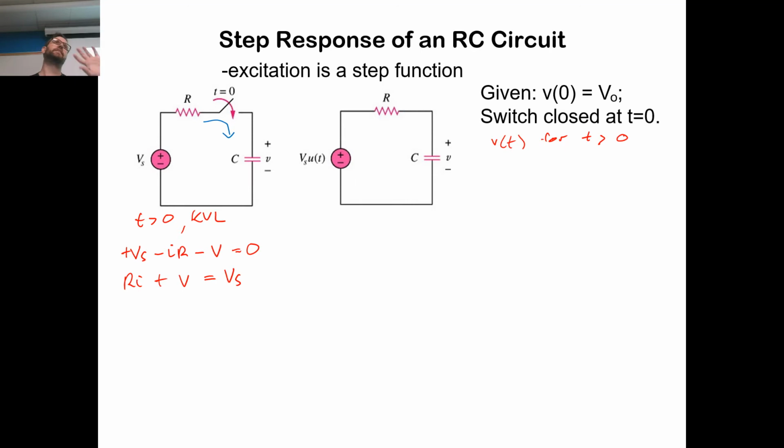We're already taking it at face value that voltage and current, we know how they're related. And we also know that current is in series here. And so the current through the resistor I is the same as the one through the capacitor C. And so we can say that it is equal to C dV dt, right? This simple step here, without having to do it in terms of charge, makes the derivation several steps simpler.